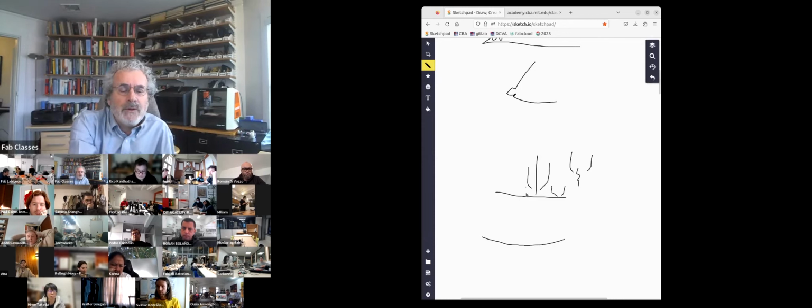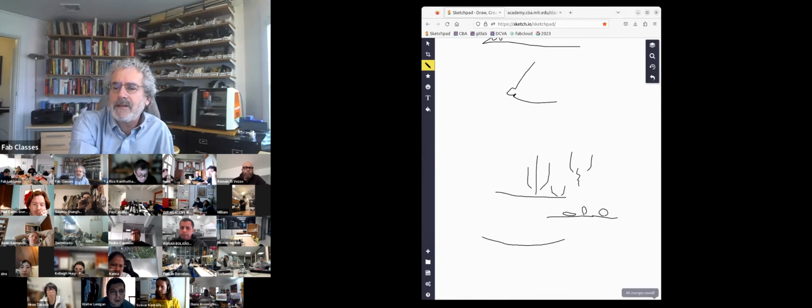So when you get close to it, if you print too close in side view, what you print is squashed very thin. If you're too far away, it's not even really sticking. And there's a happy place where when you print, it's just sort of slightly squashed to be the right distance.